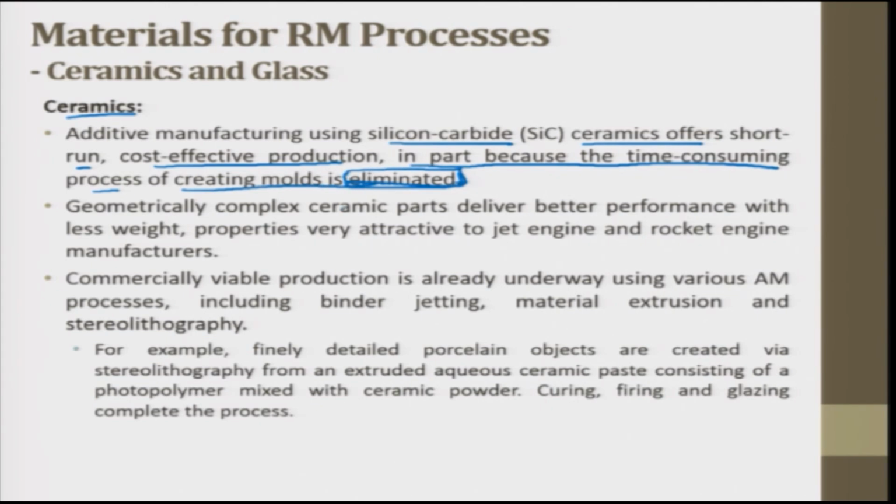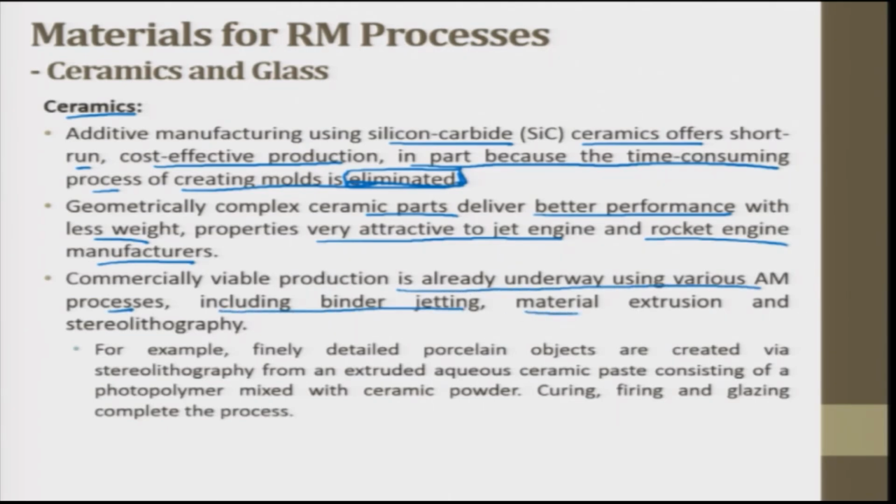So the molds are not to be made, so these are cost effective. Geometrically complex ceramic parts deliver better performance with less weight. Properties very attractive to jet engine and rocket engine manufacturers. Commercially viable production is already underway using various additive manufacturing processes including binder jetting, material extrusion and stereolithography.